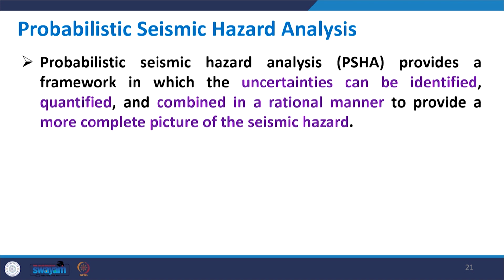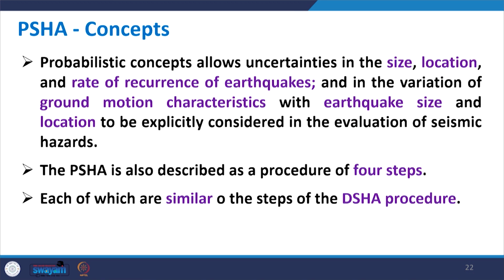As the name suggests, probabilistic seismic hazard analysis provides a framework in which the uncertainties can be identified. This is one of the issues which was missing in the DSHA. They are identified, quantified and then combined in a rational manner to provide a more complete picture of the seismic hazard. So, what is the concept of PSHA?